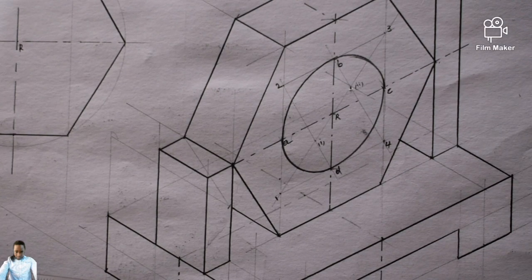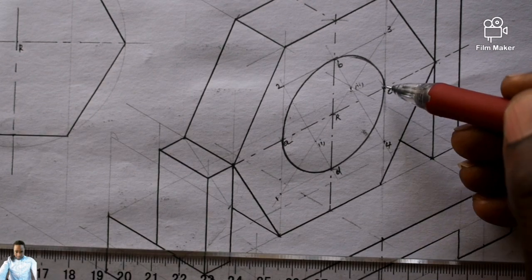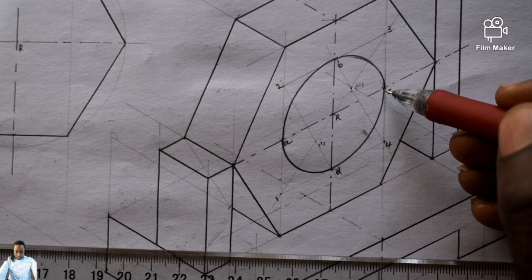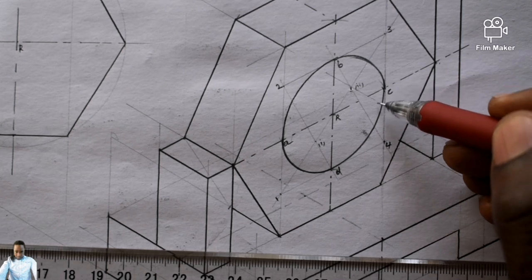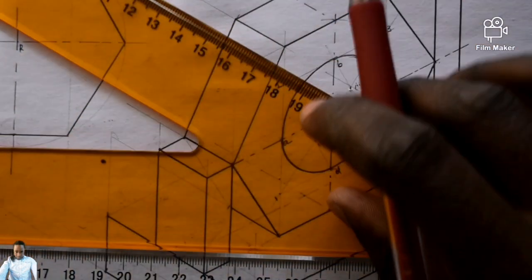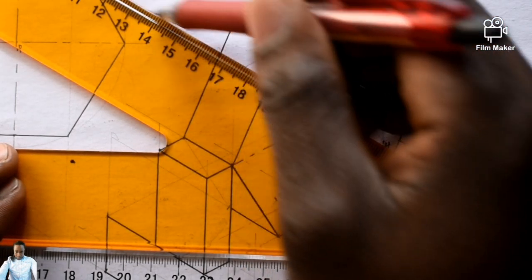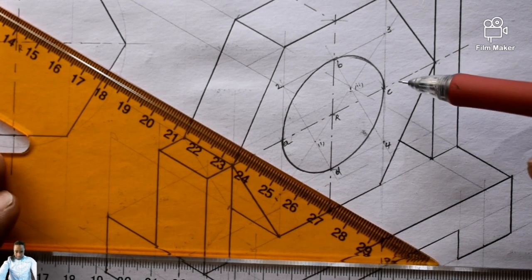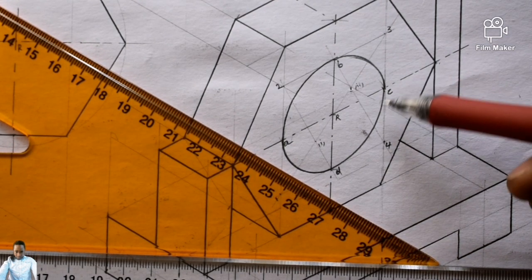We have to show the thickness of it. So to do that nicely, we are going to get the parallel arc of this one. Where we placed the drawing compass when you threw this arc, you placed it at point 2. So you're going to take it a little bit back. Then we throw this from point C to D.